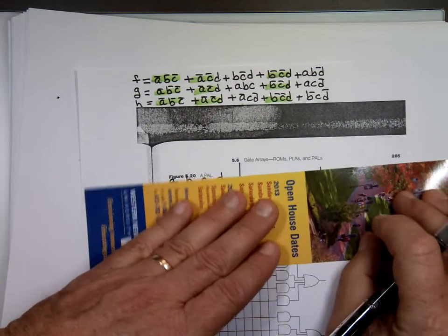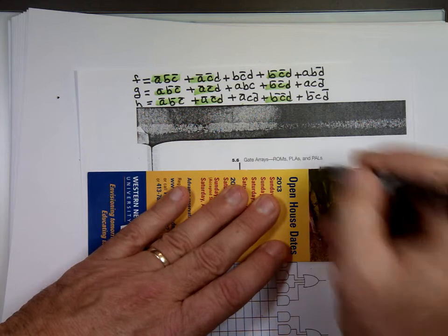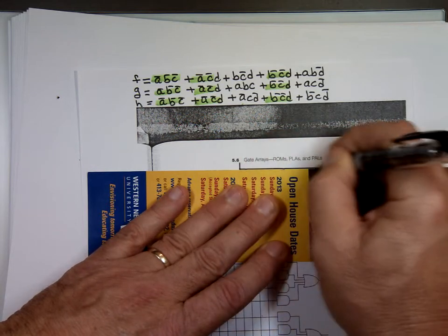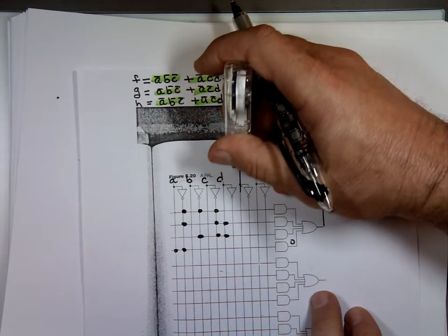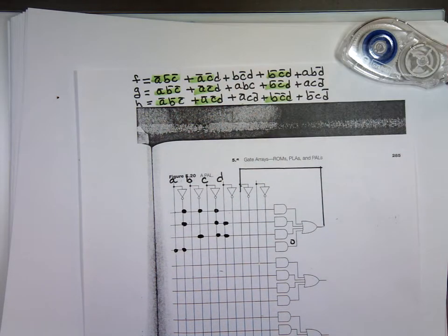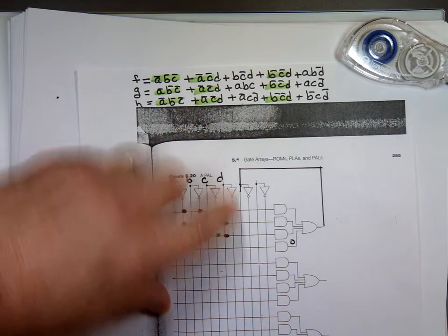Loop it around here. Make it nice and neat, clean. Got a little extra wire there. So this becomes common, actually. This becomes an input. So anytime I attach to this one, that gives me all 3 gates.